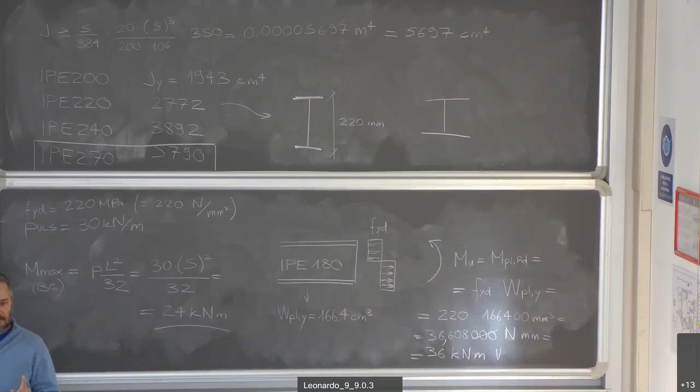Got it? Is there something you didn't understand? Yes. Tell me. When we are calculating the deflection displacement, we check the maximum displacement that the beam can withstand. We calculate the displacement that's happening. We see if it's less than the maximum one the beam can withstand. And so we say, okay, this works well. Here, we calculate the maximum moment the beam can withstand. So now shouldn't this value, which is the moment that the beam is under with a certain load, be less than that, not greater?